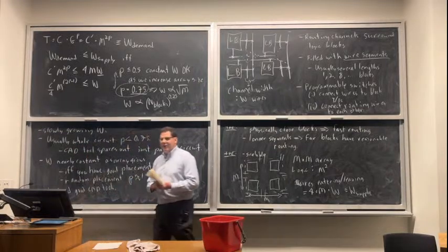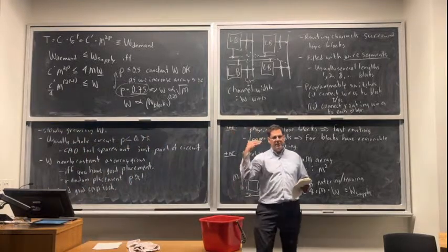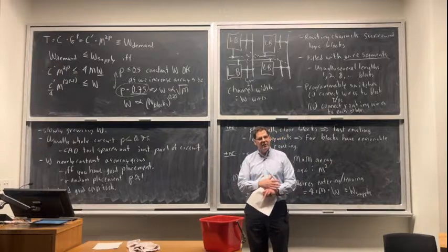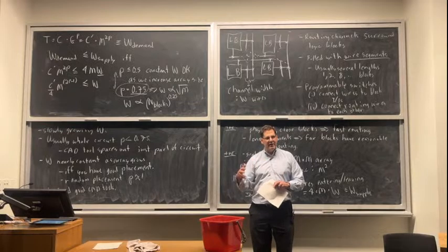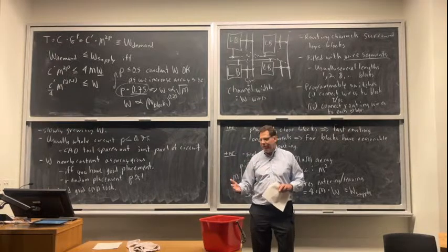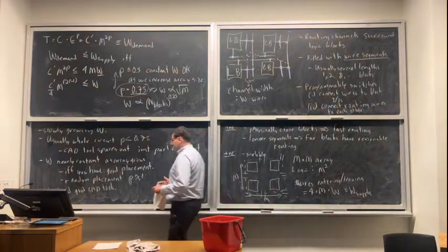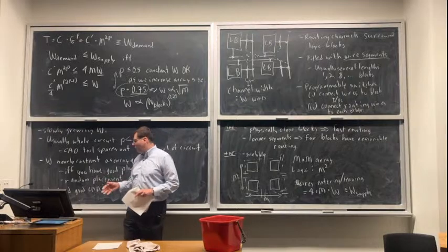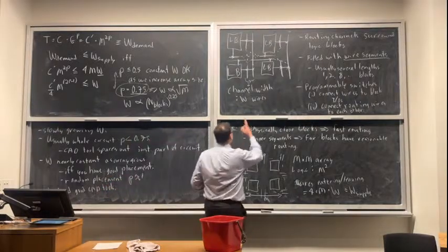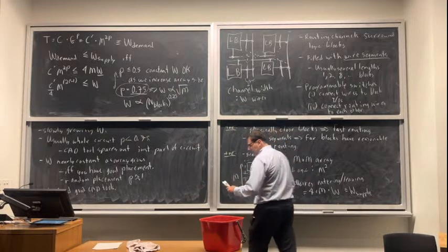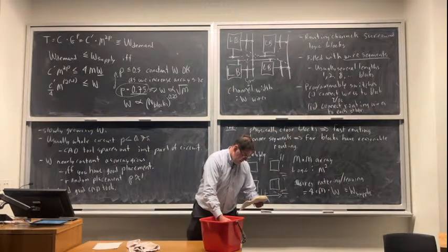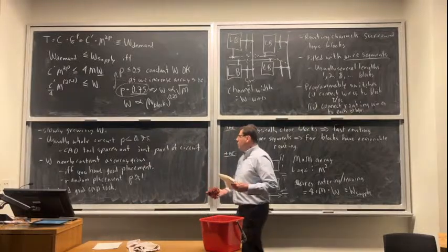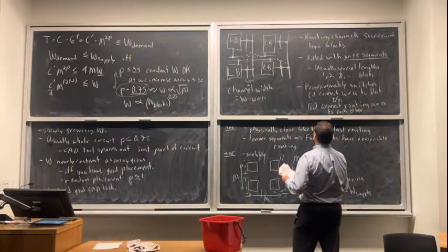So for the hierarchical FPGA CAD tools we saw, we could use partitioning to decide where to put things. Also the routing problem, like choosing which wires to connect things, is actually simpler because there are fewer choices. So the CAD tools for hierarchical FPGAs are typically not as complicated as the CAD tools for this style of architecture. So you need a very good placement algorithm. You also need a very good routing algorithm.